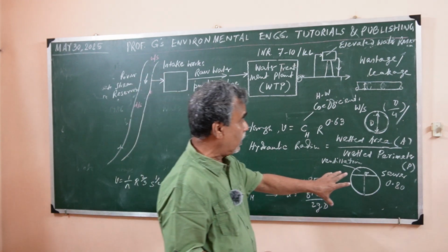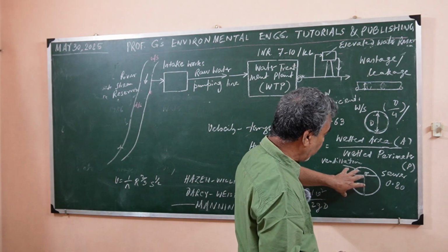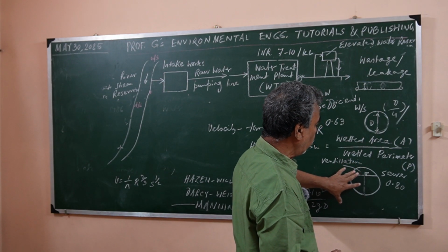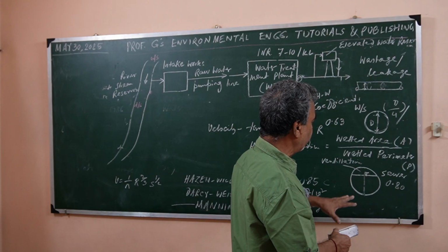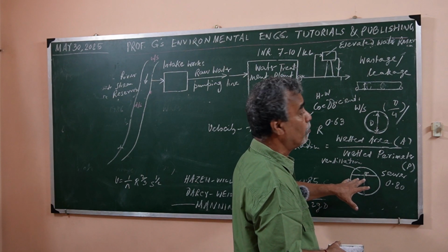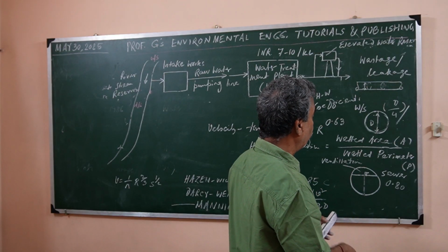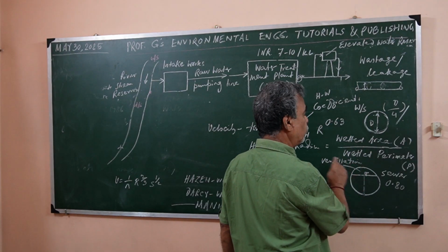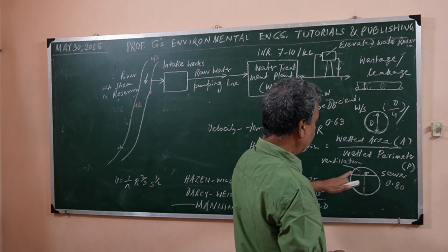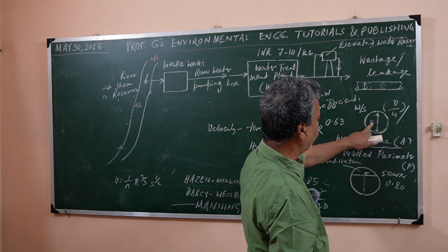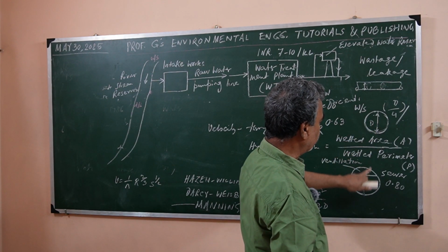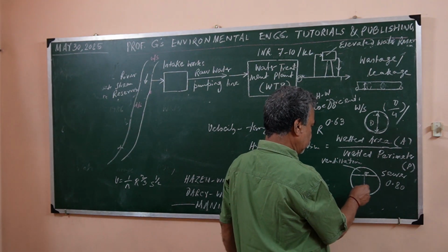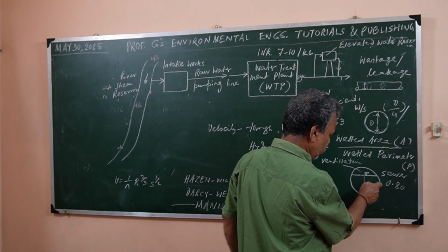So if you do not have any blank space for ventilation, then this will not have the required ventilation. As a result, this will be decomposing, and foul smell. And foul smell means the pipe will corrode and the gas will be leaking through manholes also. So these problems are there. I am not detailing this. But here the striking difference is that this is full flow, this is partially full, right? I'll come back later and explain a little more detail here.